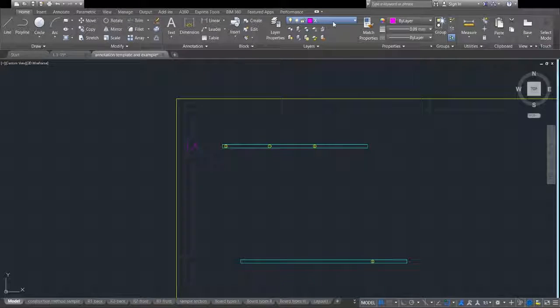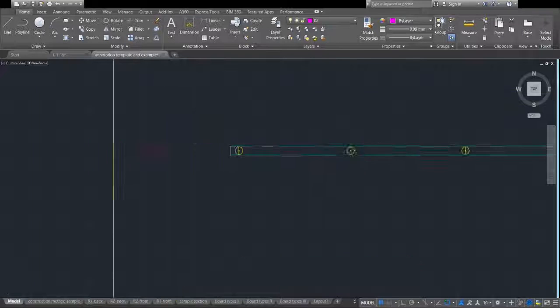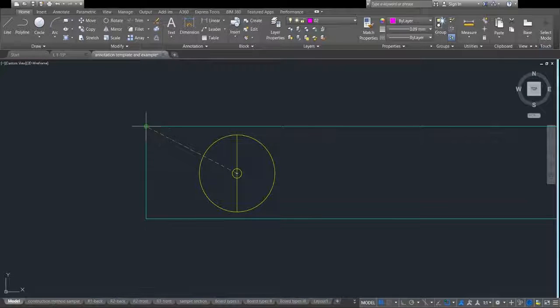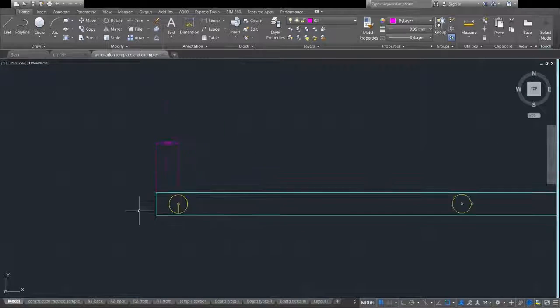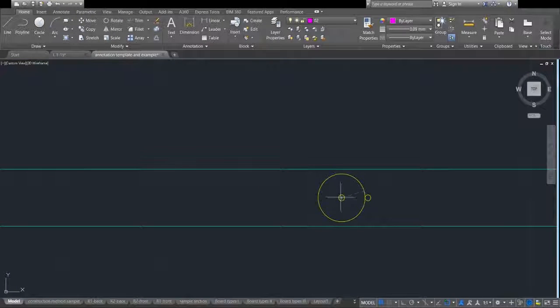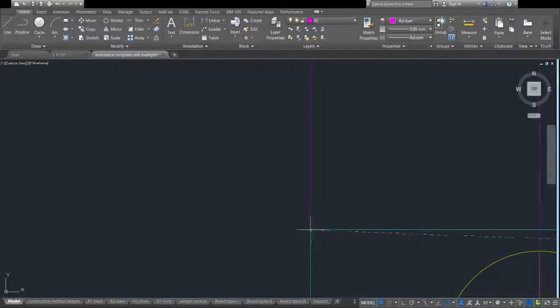we are going to move to the second layer and start dimensioning. So we have 2 dimensions to worry about. We have linear and we have angle. We've already gone over how to do angle, so we're going to do dim lin or dim linear. This is how we dimension lines. So we go from the center of this circle, this edge, and you just click there and you're done. And you have to do this for all of our screws.